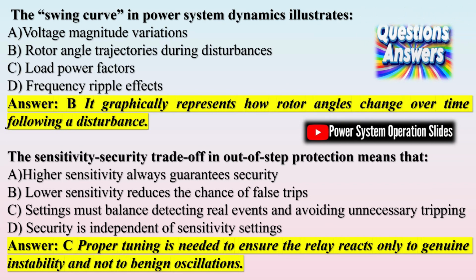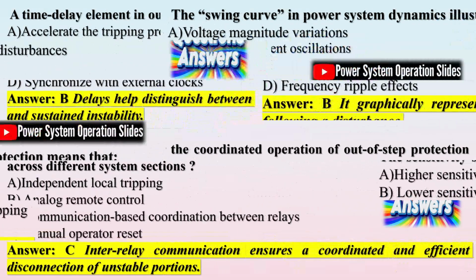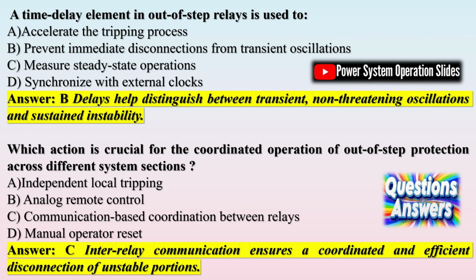The recommended approach involves several key steps. Stability and location analysis: transient stability studies help determine system constraints and identify areas and generator groups that are susceptible to out-of-step conditions. These studies also pinpoint optimal locations for OST-OSB protection based on the behavior of the apparent impedance, which is influenced by MW and MVAR flows in transmission lines.